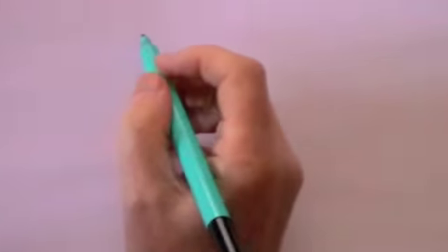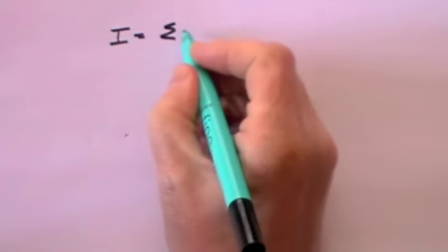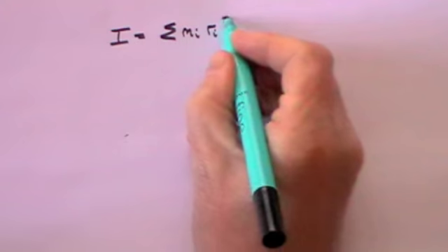So let's take some basic two-dimensional shapes and ask ourselves, what is the moment of inertia of that shape? And of course, that will depend on where you do the pivoting. I remind you that we determined that the moment of inertia is sigma mi Ri squared. That's the mass times the distance from the origin for all the masses associated.